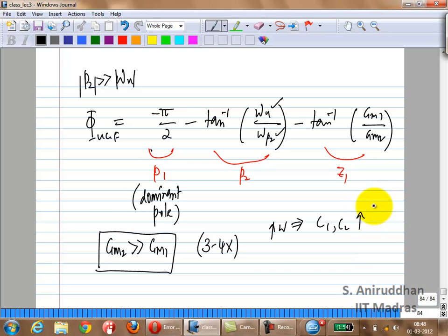So you again come back to the same old point. You have to increase the current. Same old problems with it. You increase the current, then you start hitting swing limits. The trade-offs are very similar across all of these, right? If you want higher speed, you have to burn more power and trade off with swing. Those trade-offs are very common across all the op-amps we have seen so far.